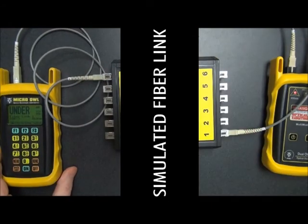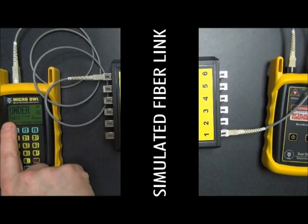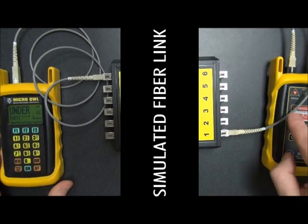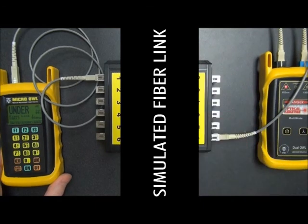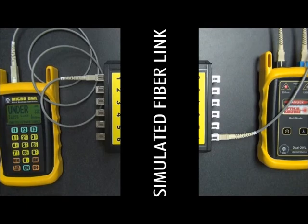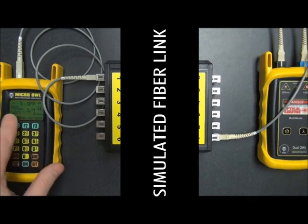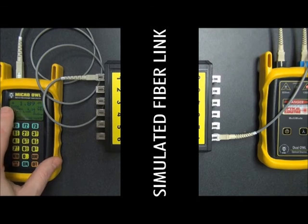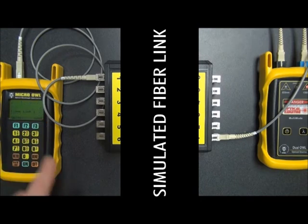Okay, now you can see that there's no light coming in. That's because we are not using this 850 nanometer reference wavelength anymore. What we need to do is press the wavelength button on both units to set to 1300. So on the light source, it's this lambda button. And then again on the power meter, now I can see you're taking a reading here, but it's wrong because you have 850 nanometers set. You need to make sure that you remember to switch this to 1300.